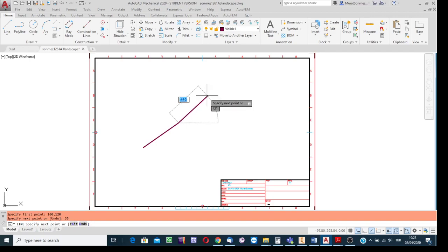Well, the new line is to be created in the down direction, extended to the right, for instance. And then write its length. Its length is, say, 100 millimeters. And then click on the Tab key. Why? Because the number which I wrote is the length, and the other number is the inclination angle.